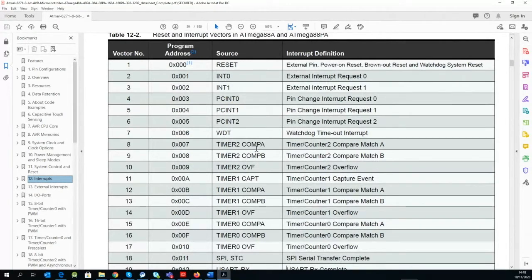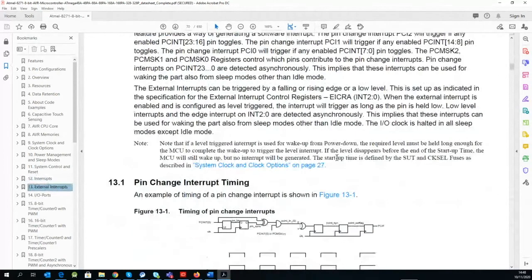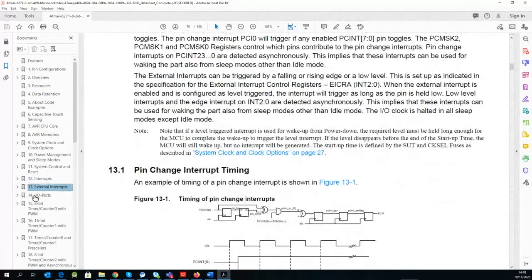You notice there are timers in there. You've got 3 internal timers that you can make use of to configure and to generate interrupts or to do some timing in general. I expect you to use interrupts for the assignment when it's released, and it will be quite specific, or it may just be embedded as part of it, and you would have to figure out what you need to use in that sense, and how to use external interrupts, because you can use both internal and external interrupts. For external interrupts, I'm referring to things like external events, like a button press or something like that.